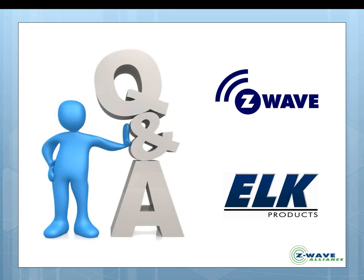There are a couple of companies that have just released repeaters. That's all they do is repeat. They don't have a switching function of any kind at all, and they're actually configured so that you can screw them down to the wall plate so they don't get removed. So anyway, any Z-Wave product that's line powered will work for you. If you're working with door locks, make sure it's a newer one that supports that beaming feature. You can find all those products and all that information on the Z-Wave Alliance website.